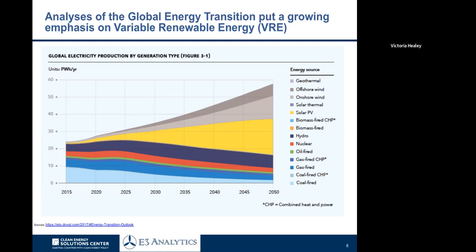Conventional power plants like gas plants, oil, diesel, nuclear, well, to a varying degree, nuclear and hydro can be dispatched. They can be turned on and scaled up or scaled down, again, to varying degrees, depending on the technology. Variable renewable technologies like wind and solar, because they rely on renewable resources that are available in the natural environment and are dependent on weather, are typically considered must-take resources.